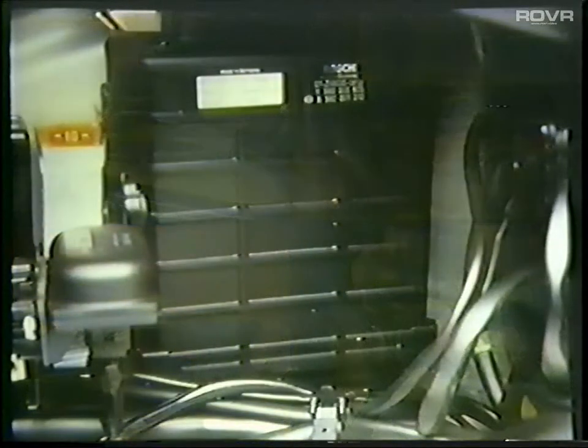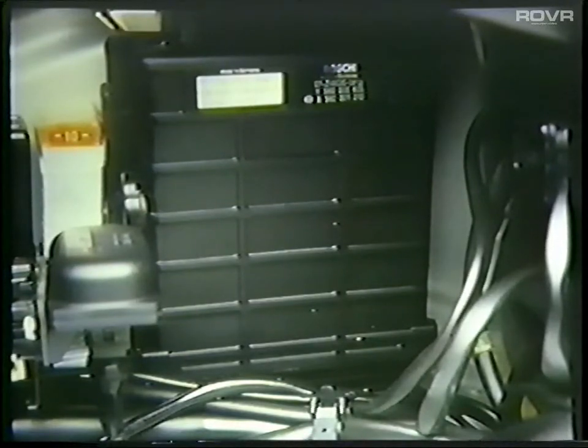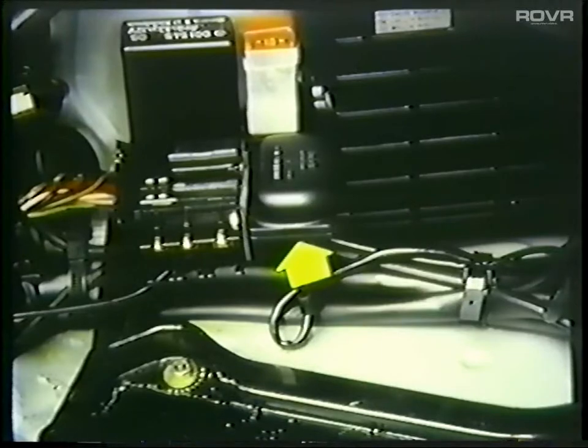To begin, it can be said in general that the important distinction of the CIS-E is that it is a refined version of the familiar CIS system, but with electronic sensors to provide more precise fuel delivery. Signals from these sensors are fed into an electronic control unit. The ECU is responsible for processing the information received from the sensors. The various sensors include one for measuring the barometric pressure, and one that transmits information on the movement of the airflow sensor plate during the warm-up period.